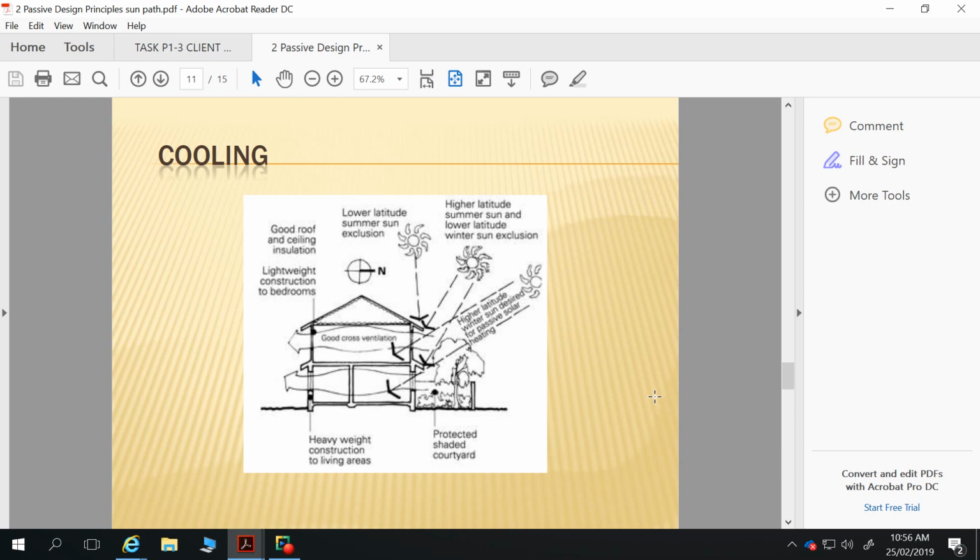And then also you get further radiant heat. As your sheeting is quite hot, it radiates a shorter distance to your ceiling. But also by increasing the pitch of your roof and increasing the volume inside your ceiling there, you can provide better thermal comfort in a place like South Australia.